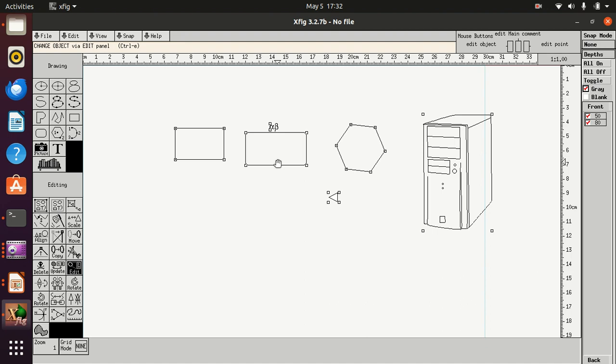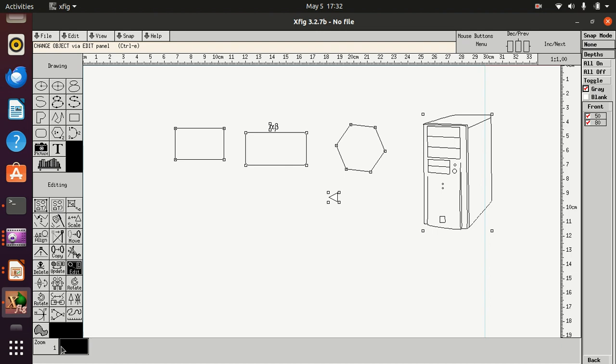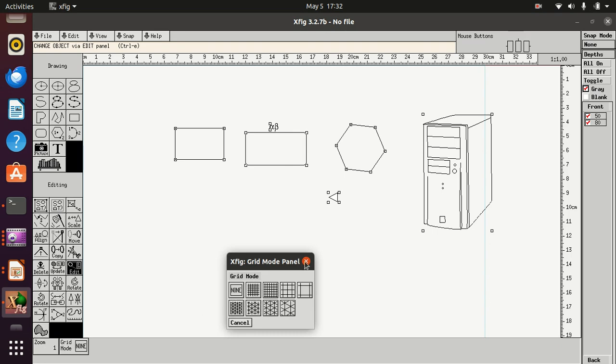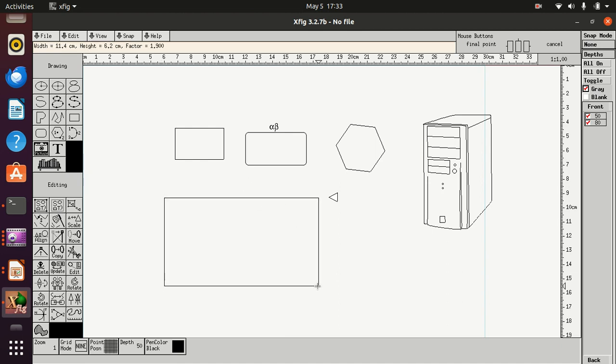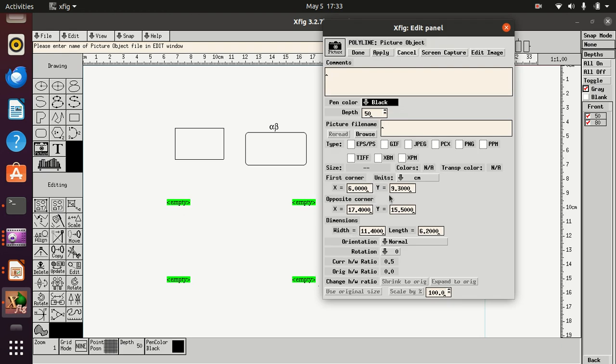That's all the beauty of pixels, but even the grid also you can see, the size of the grid you can choose between the pixels. I mean, that's the beauty of this Xfig software. Pixel by pixel you can edit, you can draw the figures, block diagrams, flowcharts, right? And also you can include some pictures. That's another advantage. After selecting the picture, draw the area where you want to have the picture. And what types do you want to include? EPS, GIF, JPEG, whatever you want. You mention it, it will filter that.